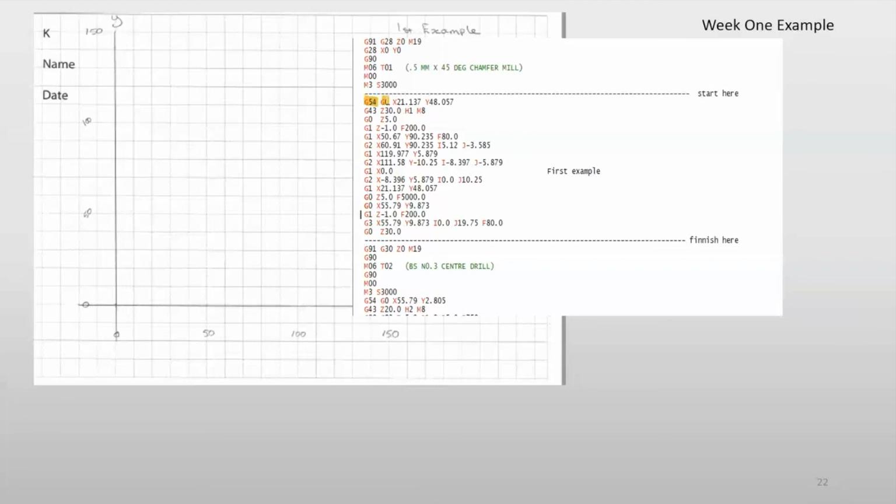So you make it G0, G54. How do you zero it? You want to do it as fast as possible. You don't want to cut anything. So I put G0. Usually this is the first line of the code in a CNC machine, G54, G0. And I will find the points that I want to go to and make the machine zero. So assume that's the X and this is the Y. This is the XY plane, G17. So you find the first one.